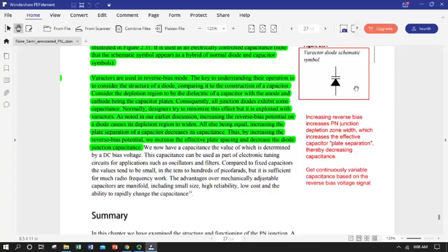But it's also a good reminder that every time we use a PN junction, we're adding a capacitor to the circuit. And when we look at frequency-dependent applications later on in our studies, that becomes really important when we talk about switching speed and signal processing. Just remember, every time you have a junction, you have a capacitor, and you're having to charge and discharge it.